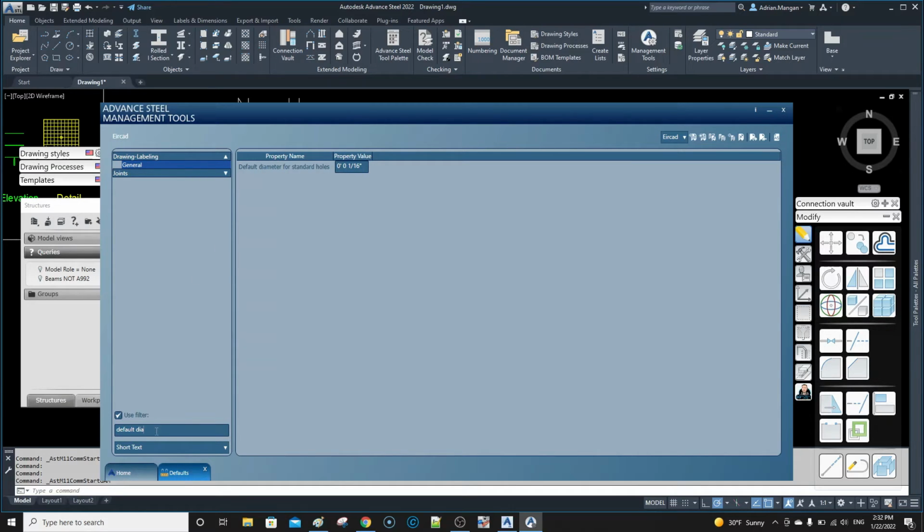There's another similar one for weld size. So we go to weld size, and the weld size here is a 1/4 inch, and this is kind of the same idea. So we want to also change this to 1/16 because now it'll show up all the welds that are not 1/16. So it'll show up every weld because it's not going to recognize this. So it kind of forces the system to label all the welds. And then also 1/16 ones will not be labeled.